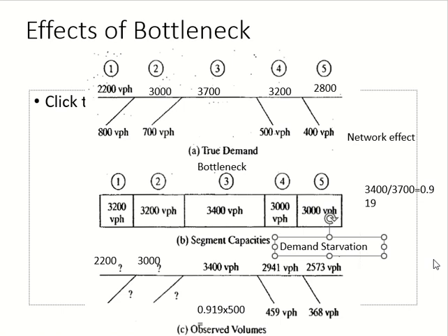That's God's way of balancing things. Okay, which is this one. Clear? So whenever we have a breakdown, after the breakdown, the flow becomes less than demand and less than capacity, meaning the situation on this segment is even better than what you were expecting.